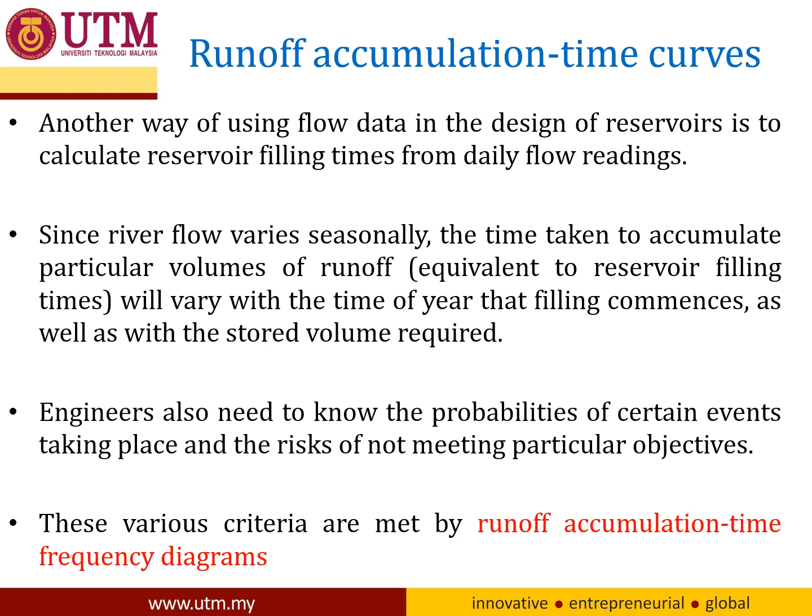probabilities of certain events, the probabilities of how much volume of runoff is usually there in a certain river going into the reservoir. So you can do this by using a runoff accumulation time frequency diagram. This is quite similar to frequency analysis. The previous chapter was on rainfall frequency analysis, but here it is for flow.